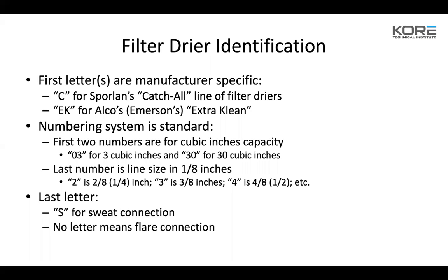So whenever you guys are doing dryer change outs, if you have one on your truck, always size up. Don't ever size down. Meaning if you have an 083 on there, and you have a 163 on your truck, swap it out with a 163, but then just adjust the charge accordingly. Don't go the other way. Don't go from an 8 cubic inch down to a 3 cubic inch. That's never good for the system.